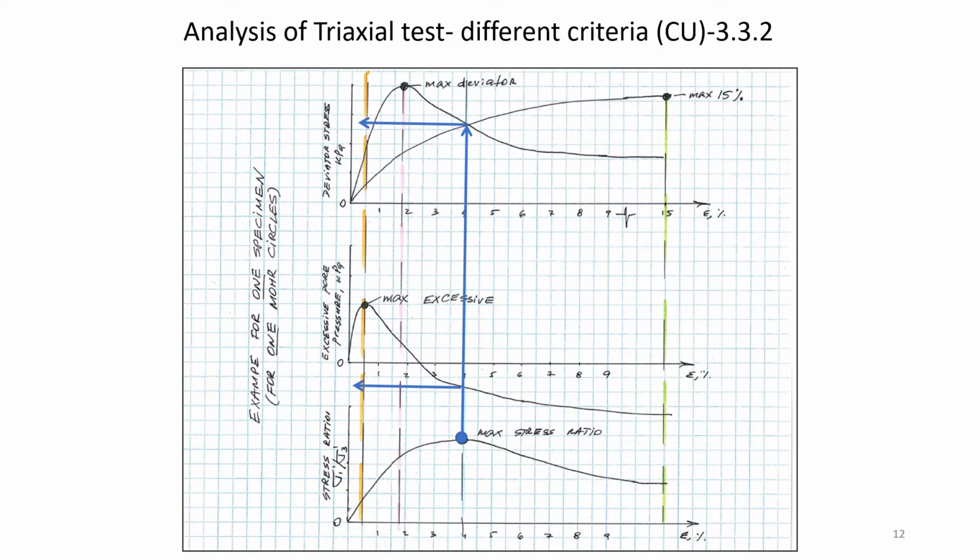By the way, just take a look. In this case, you have negative pore pressure. That means when you calculate your effective sigma 1, it is going to be sigma 3 prime minus u. This one is u. Okay, so it's going to be plus. Just keep it in mind. It's very important.